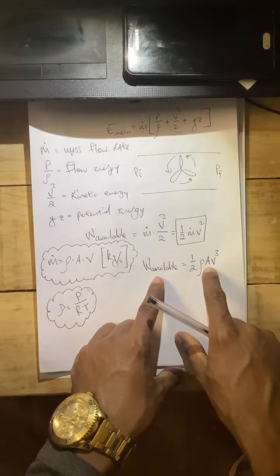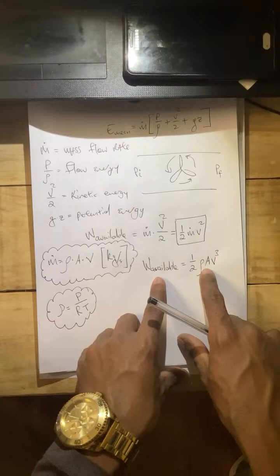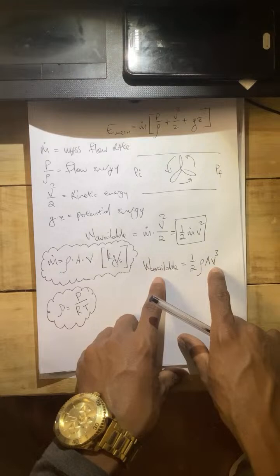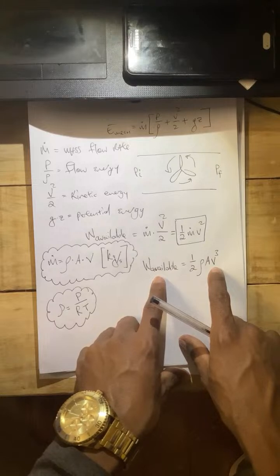Another way of defining this area is by saying the radius of the blades on the turbine, but that is a linear relationship. It's a one-to-one relationship. The thing that actually carries the meat on the bone is the speed. Because if you look at the speed, let's assume the speed is 1 to the power of 3. It remains 1. It's not a big deal, meaning your multiple is 1. But now let's make the speed 2. If you say 2 to the power of 3, you get 8. Your multiple went from 1 to 8 if you just double the speed from 1 to 2.